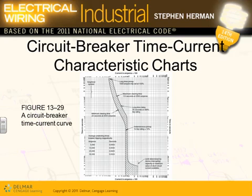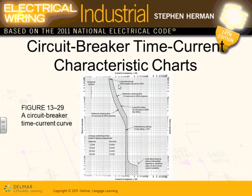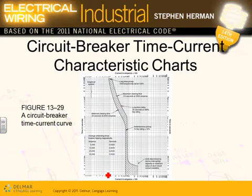Ground fault? Okay, now, Matt, if you remember, in the commercial project we have a time current characteristic curve. Every circuit breaker has a time current characteristic curve. This curve will decide how fast the circuit breaker will trip, and I'll show you in a second here. So the higher the current, the faster the circuit breaker will trip.